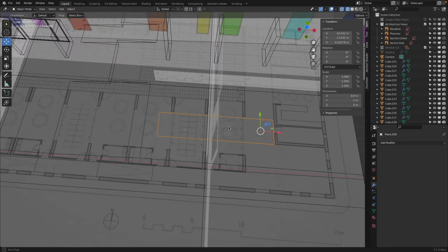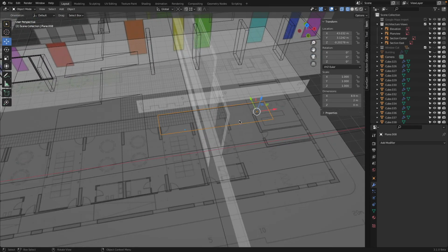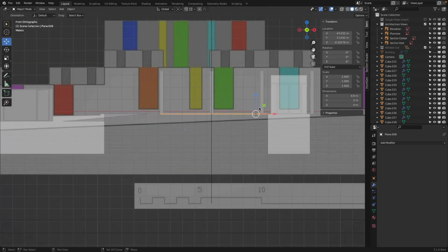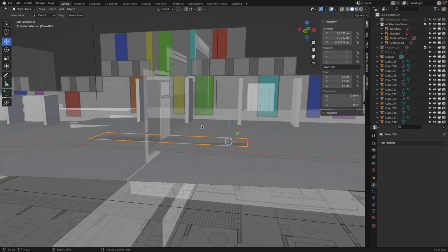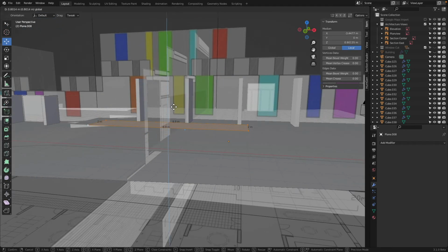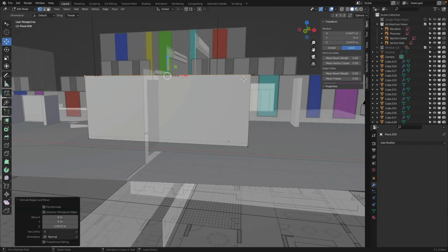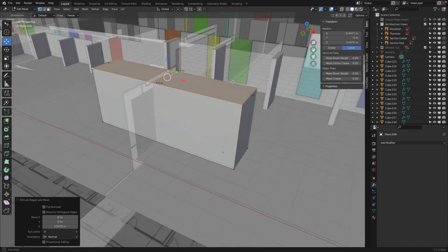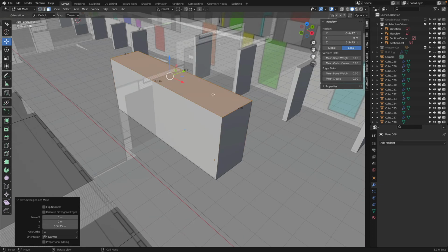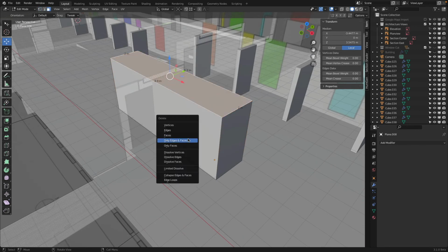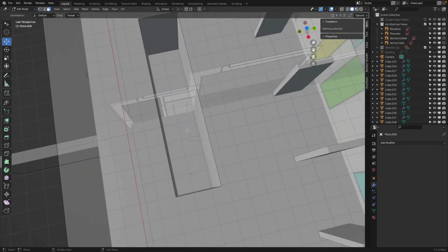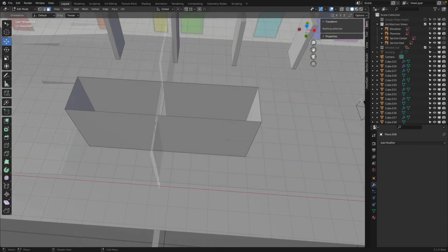Okay. Thank you. Actually, I will show you one way. That's the best way even to do. Then we can go into edit mode, select everything, move E and extrude this up. Hold control maybe to there. Yeah, now we have this face, X and delete face. Select this face, X and delete face.